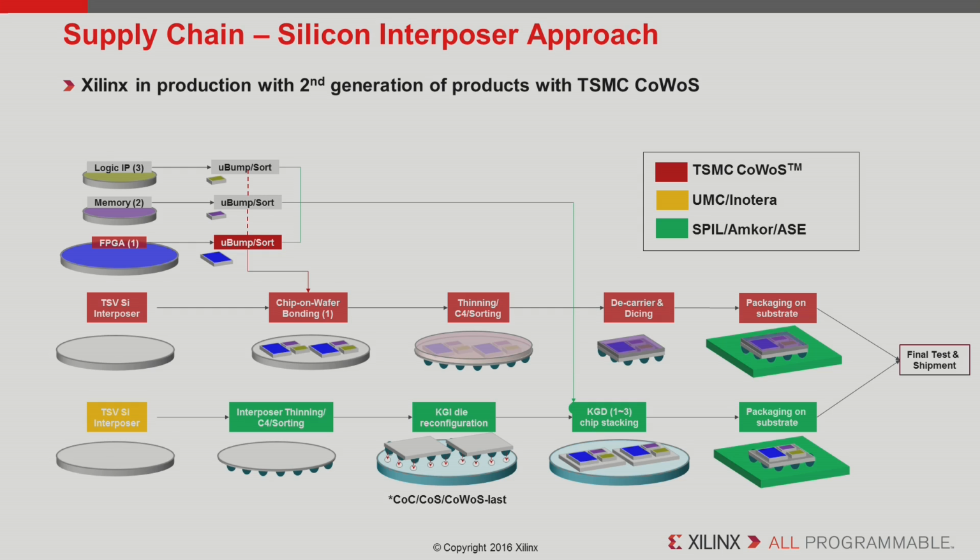So in this configuration, it goes through the assembly and molding and then carrier bonding. Then the interposer wafer is thinned to expose the TSV and the C4 bumping, and you dice it and package it. So if it were OSAT format, then clearly the interposer wafer has to come from a foundry, and you need to find a partner. So the supply chain is getting a bit more complicated because now you could have dies coming from TSMC, memory from, say, Samsung or SK Hynix, and interposer wafer from another source. And the integration all happens at the assembly provider.